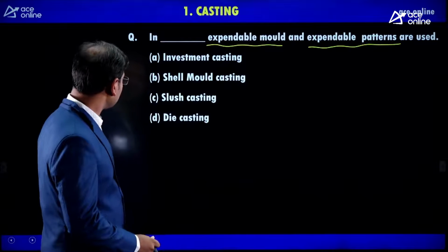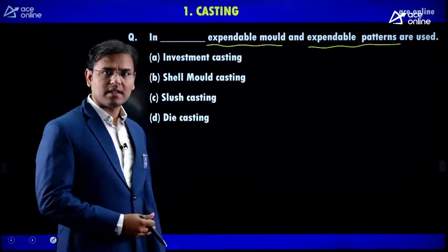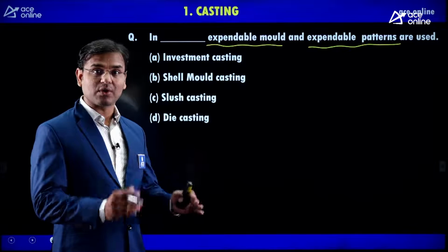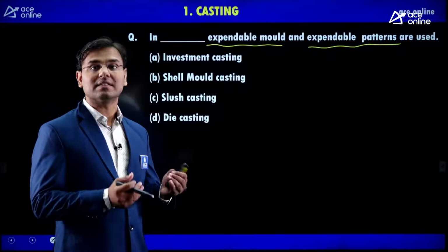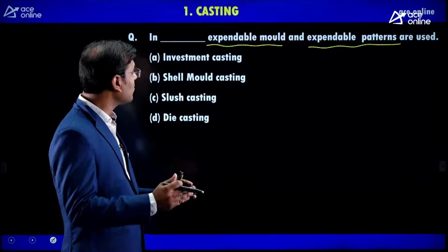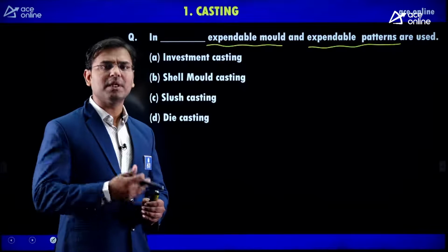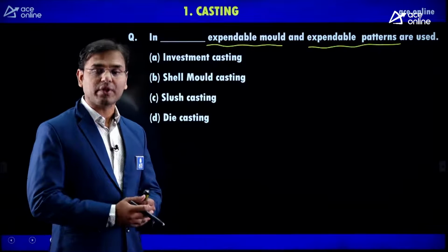Then definitely, guys, the sand mold, means the mold which is made by molding sand, that mold we are going to break and we are taking the casted component. Then all the sand molds are expendable molds. And next, the expendable pattern. Expendable pattern means the pattern also we are going to break.